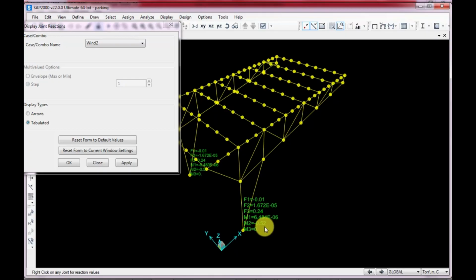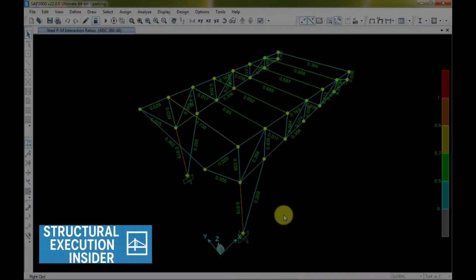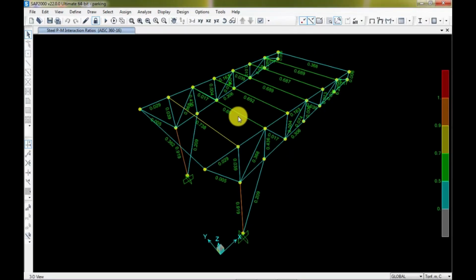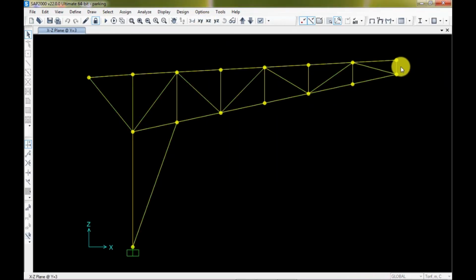Now we move to structural optimization. From design results, we observe that several members are over-designed. Display PM ratio, demand capacity. We notice columns, OK, beams, OK, truss diagonals, very low utilization. This indicates that some members are not efficiently designed, especially diagonal and vertical truss elements.